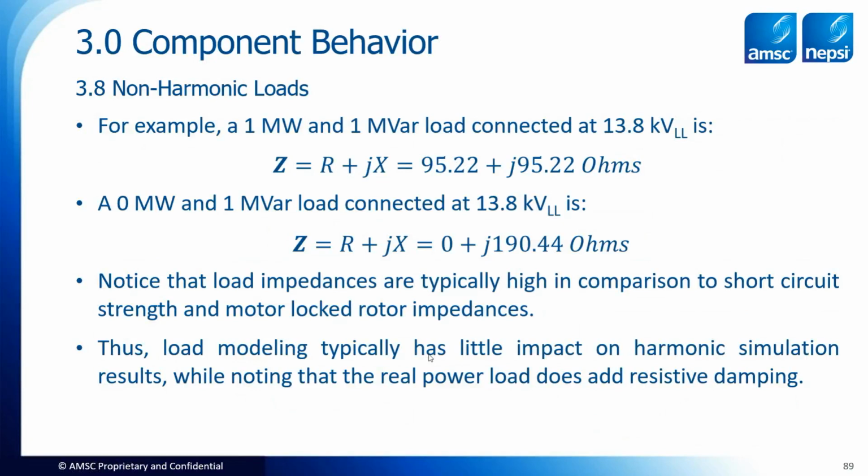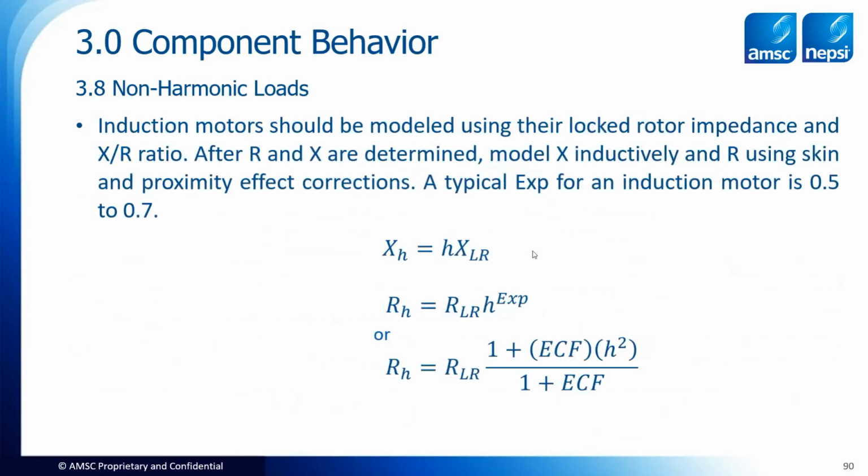So having loads modeled, especially the real part, will add damping, which is very realistic. Real power loads do add resistive damping for harmonic simulations. But again, their values of ohms are typically very high in comparison. And I'm going to show that here in a couple slides.